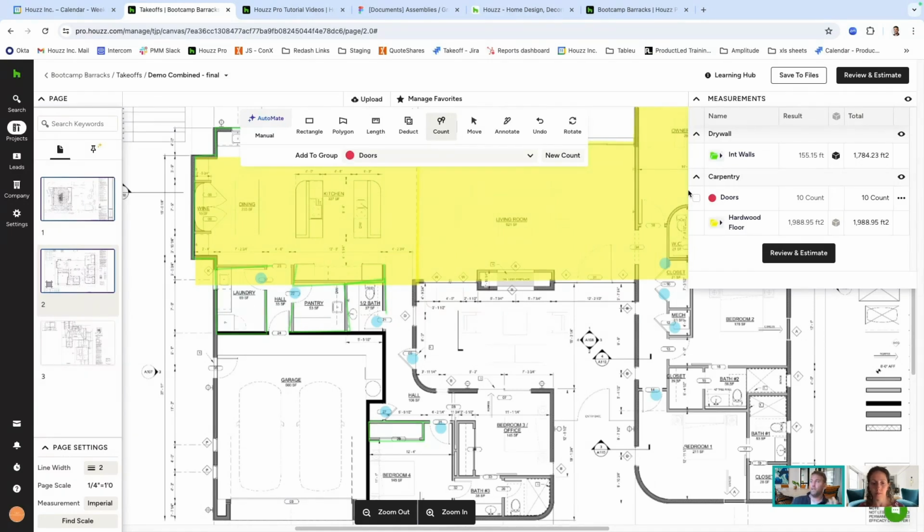difficult to remember everything. And what I should say as well is, if you have groups in their carpentry category, and you're doing those 10 pages out of the 100, and you're counting doors on 5 of those 10 pages, once you're finished, you can merge all of the groups together to get project totals. So if you've got 10 doors on this floor, 12 on the next, and 8 on the top floor, then you'll merge that together for project totals, and it just gives you really good quick access to what you're going to need.